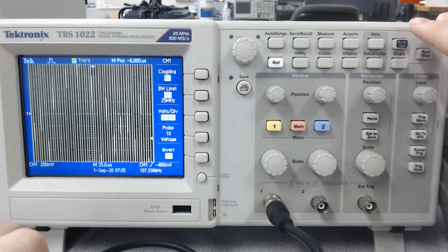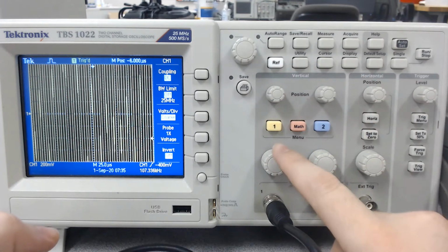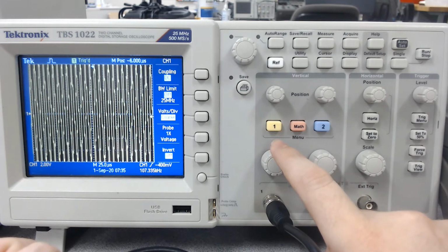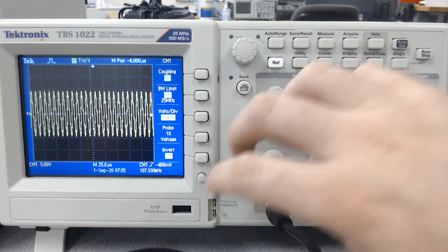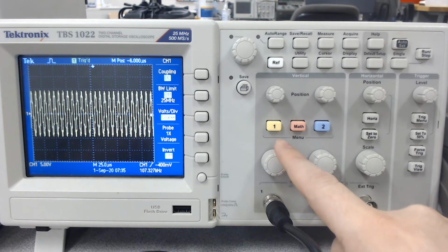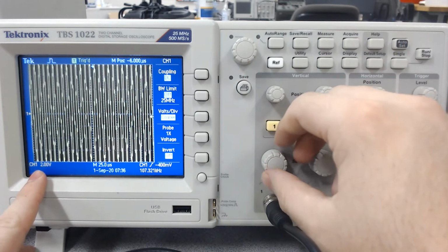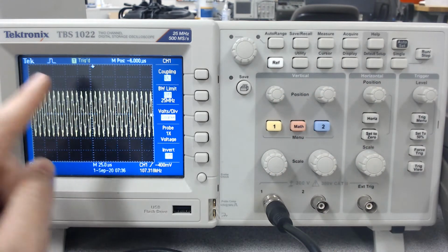So what we're going to do first of all is adjust and play with it. This right here is the vertical scale knob. As we adjust this, it's making that scale higher or lower, so it's zooming in and out. It is important to note that anything on this oscilloscope is not really affecting the signal other than input impedance, which we'll cover, I think, in lab 3. But as you change this, obviously down here in this corner, the voltage is changing. But what that voltage actually means in this position right here is how big each square is.